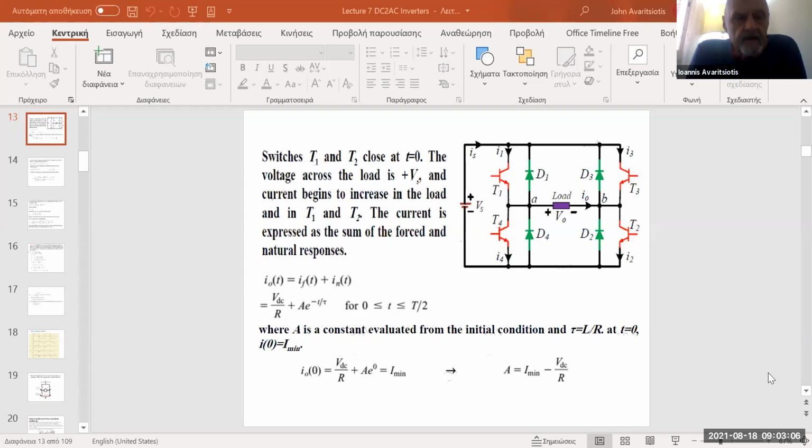And you remember I gave you as a quiz, and also I explained to you in detail a switch which was switching on and off an inductor, and you remember we used this snubber circuit in order to protect the device, whereas all the energy which was stored in the coil was finally transformed to heat in a resistance which consisted of this snubber circuit.